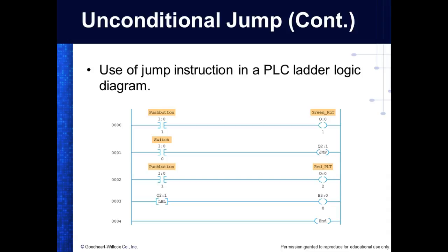That makes sense. So what we have the ability to do is jump forward, or we can also jump back. So I could repeat a run. Let's say I wanted to repeat a run 10 times. Well, I could jump backwards. I could have a counter every time it comes through, and after the 10th count, I cut off the jump. Then it goes back to the section. So when this is true, I run a run 10 times, or I run a section 10 times. Right? You understand?